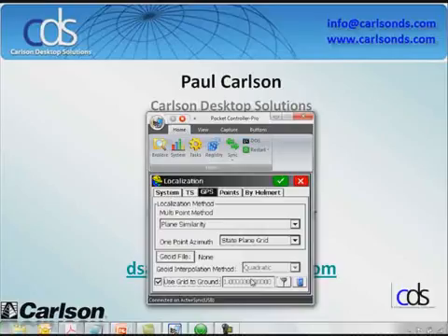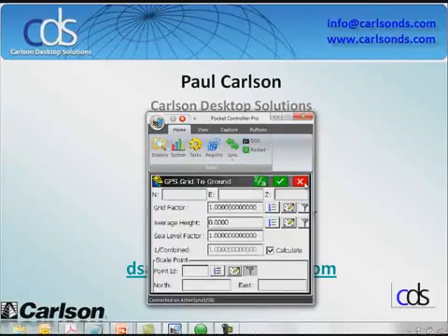You have the ability here to key in your scale factor. You have the ability to read from the GPS position and have it calculate a scale factor, or you have a calculator which will let you calculate your scale factor. Okay, and because I'm using GPS, this was always a point of confusion for people. Which way am I going? Is it grid to ground? How do I enter it? They kind of cleaned this up a little bit too and said if you're using GPS, we're going from the grid to the ground. Okay.